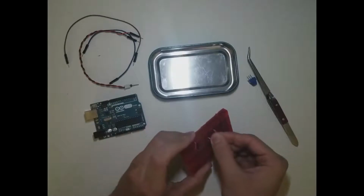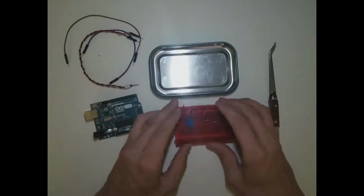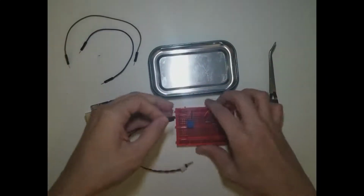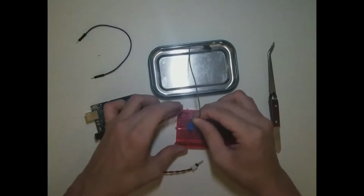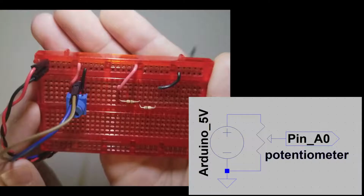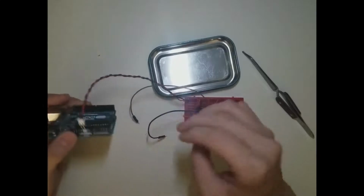Here's our circuit with the 2 wires in the middle of the potentiometer connecting to A0, and the other one is going to connect to our oscilloscope. Right now, no wires are connected to the output of the 2 bare resistors, but we'll look at those later. We have our positive power, our potentiometer and the output pin, and our ground side. And of course, we have our voltage on the 2 bus lines. Let's connect this up to 5 volts and to A0.